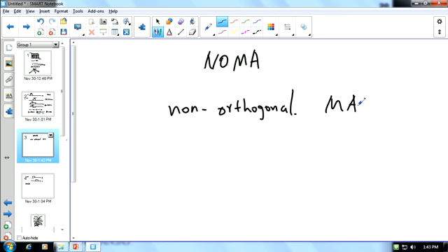We don't have unlimited time, we don't have unlimited spectrum, but we want to support as many users as possible. So we put many users in the same spectrum, at the same time, using the same code. We are using non-orthogonal multiple access, and then we use advanced signal processing techniques to separate one user from another. That's NOMA, and it has received lots of attention during the past few years. Any questions?